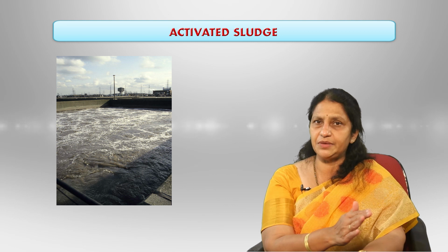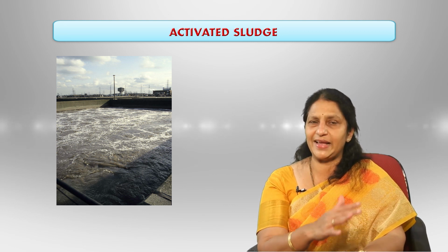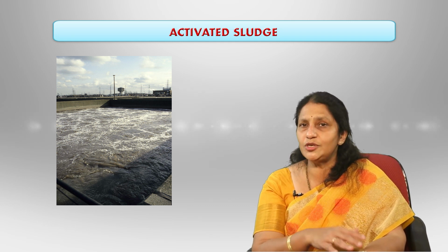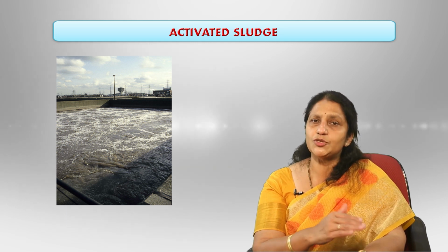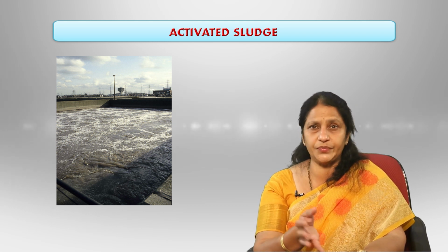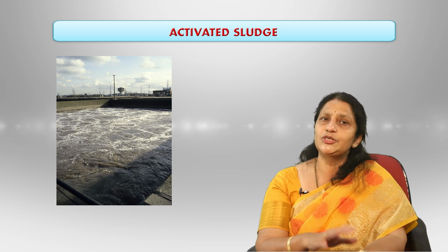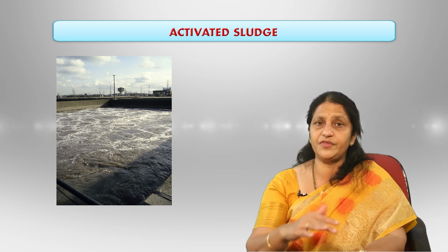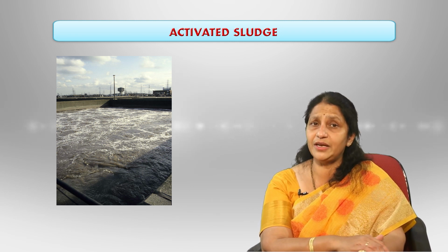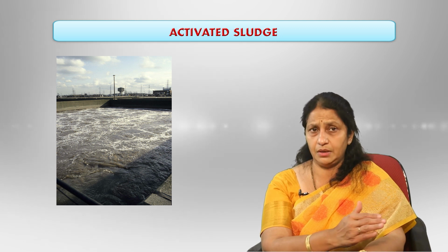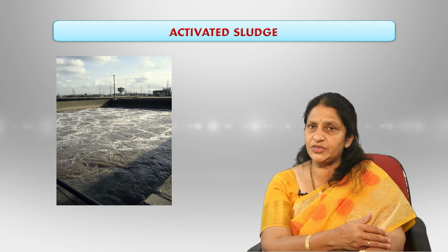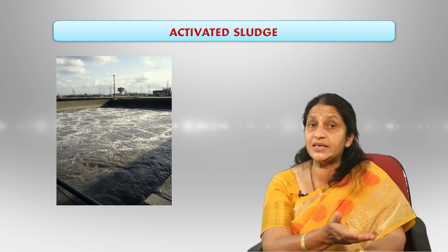During that aeration period, the activated sludge organisms use the available organic matter as food, which produces stable solids and more organisms. The suspended solids produced by the process and the additional organisms become part of the activated sludge. The solids are then separated from the wastewater in the settling tank. These solids are returned to the influent of the aeration tank, that is the return activated sludge. Periodically the excess solids and organisms are removed from the system, that is the waste activated sludge.